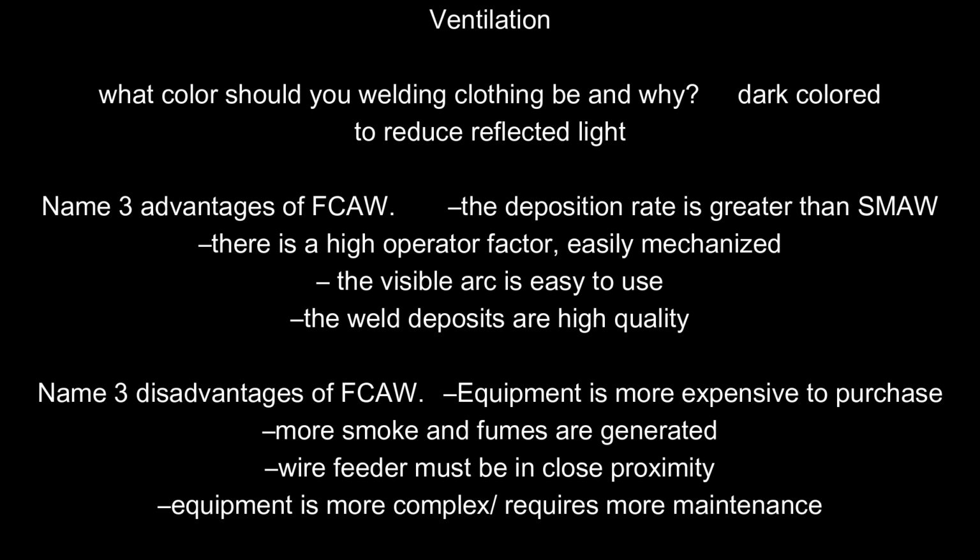Name 3 advantages of FCAW. The deposition rate is greater than SMAW. There is a high operator factor, easily mechanized. The visible arc is easy to use. The weld deposits are high quality.